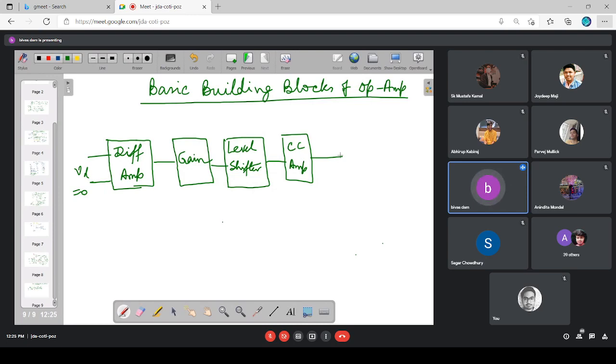But let us assume that while fabricating, those parameter values were exactly the same. But remember, these parameter values change with environmental conditions. The transistor alpha value, beta value, transistor resistance, junction capacitance, everything changes with the changing environmental condition. Is it not? I think you have to read all those things.